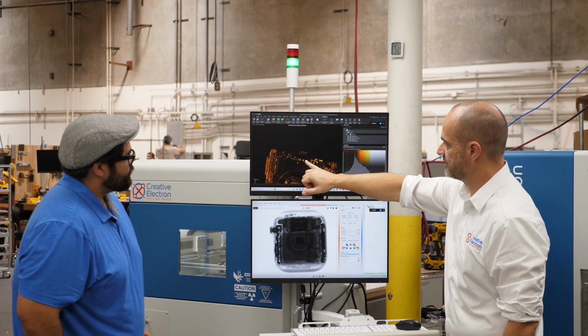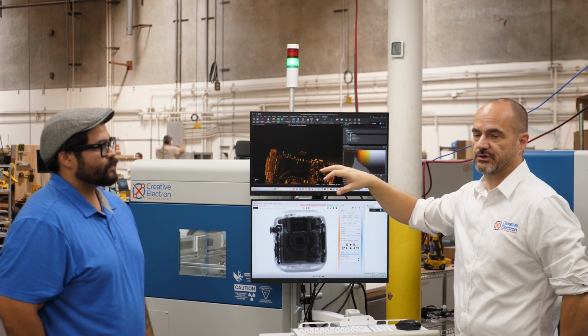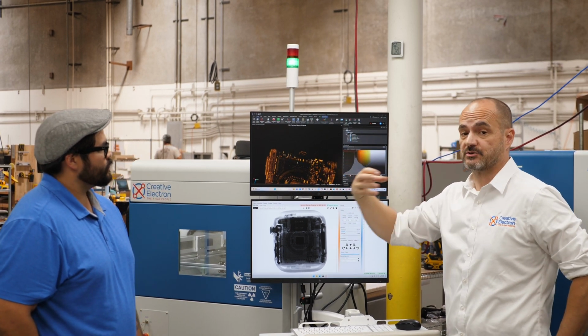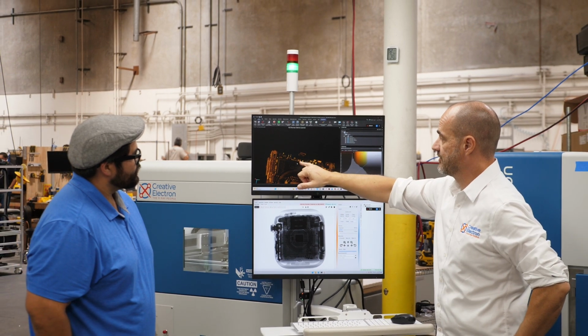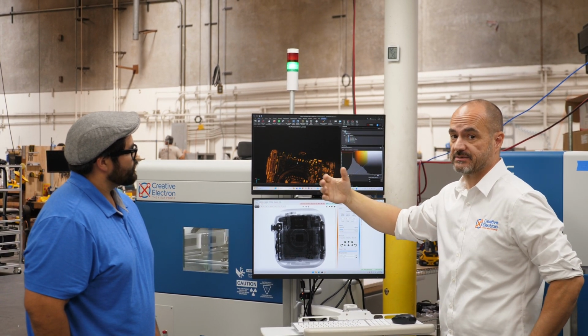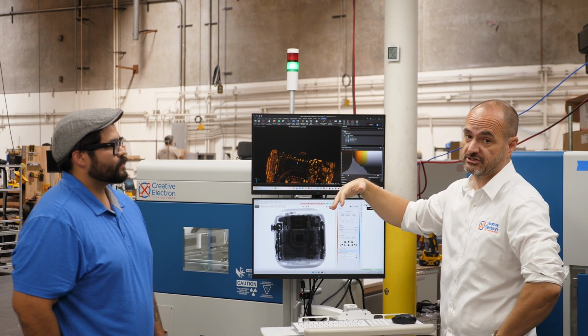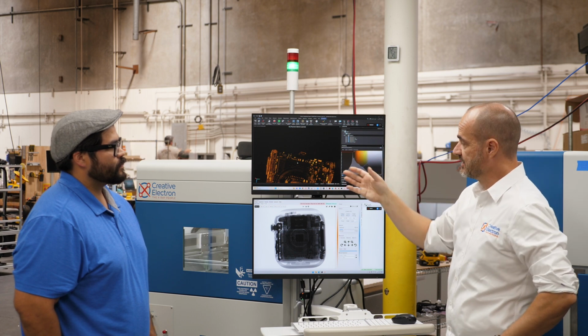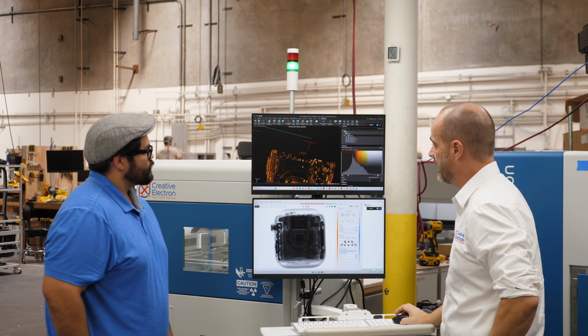Look at the level of detail. The capacitors, the inductors. You can tell a capacitor from a resistor by the fact that a capacitor has a lot of density, so it's radio opaque, and you can actually see the component between the leads. A resistor is virtually invisible to X-rays, and as you lower the power, you can see right through resistors.